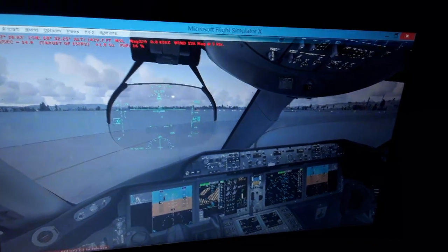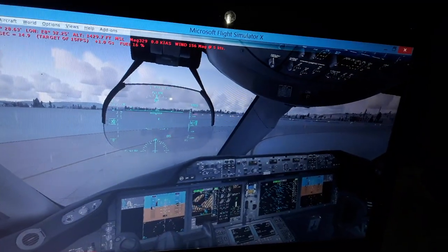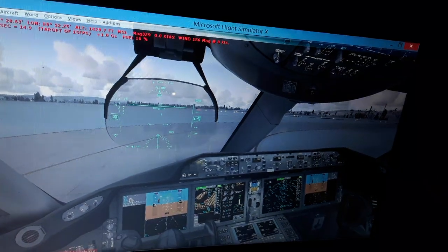You can calculate with this computer the altitude difference, how many hundreds or thousands of feet the other aircraft is above or below our aircraft, and whether it climbs or descends with respect to our aircraft. You can also calculate the closing velocity between our aircraft and the other aircraft. It will give us a warning if we have an incoming collision in the air, and we will make an avoidance maneuver using the TCAS, the Traffic Collision Avoidance System of the aircraft.